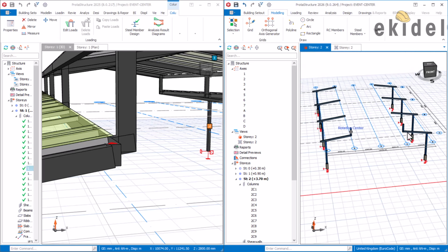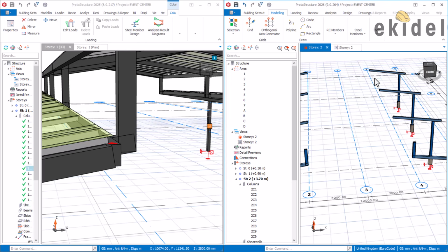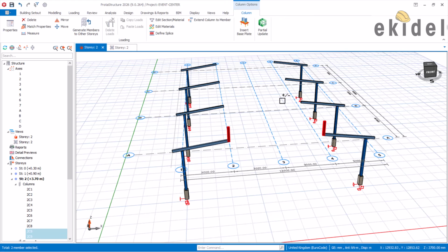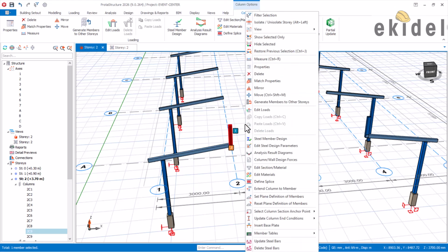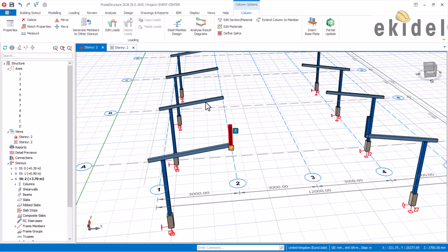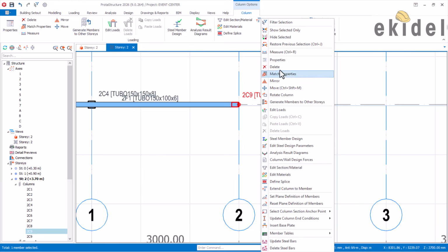So once we've achieved this other one now, we then move on to place this particular same thing here or in this direction. So by doing that now, just maximize here again. Now click on this now and I'll click on this, right click here and I will say okay, you can do that. So come here and then click on this one, right click here. Now we cannot do copy spatial. Okay, we can't do copy spatial here because only beams have the copy spatial option. So what we'll do now is to insert this column, okay, directly there. So we come back to our plan view here, then come like this now, click on this column, right click here and then say properties.